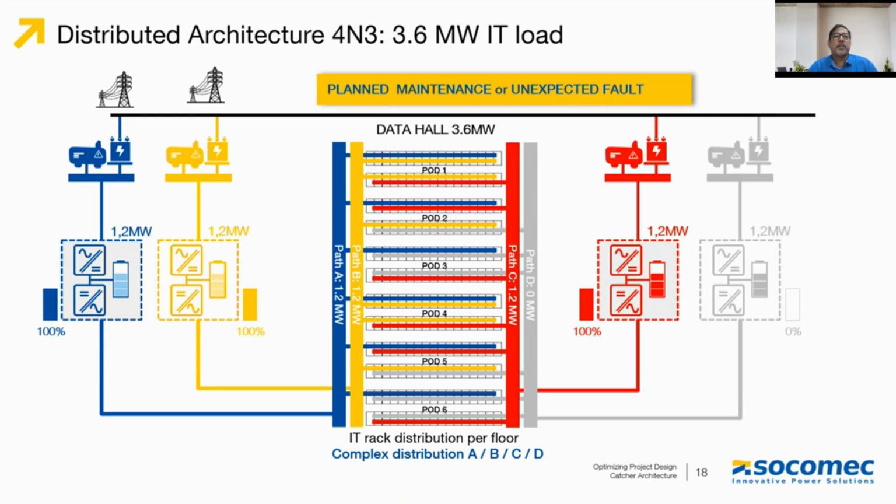So providing four parts for these servers, in case of outage of any one system, the remaining three will manage the loads. So under normal conditions, these systems will typically be at around 75% load level, compared to 50% load level in the 2N architecture.